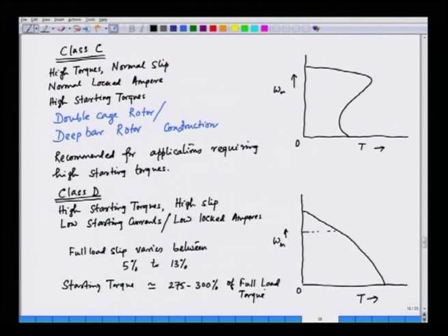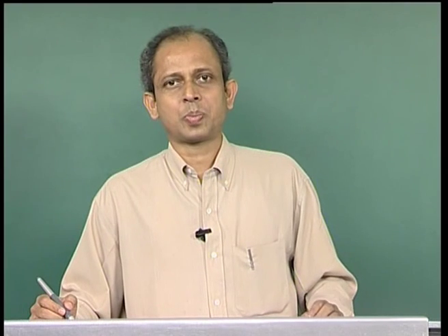So this class of motors are applied with punch presses applications. So this is basically class D motor having large rotor resistance, and they are applied in those applications where we require high starting torque. Now these are the classification of the induction motors.